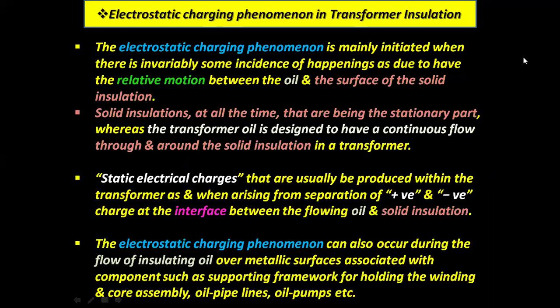Let's start with the electrostatic charging phenomenon in transformer insulation. The electrostatic charging phenomenon is mainly initiated when there is relative motion between the oil and the surface of the solid insulation. Solid insulation is always the stationary part, whereas the transformer oil is designed to have a continuous flow through and around the solid insulation in a transformer.